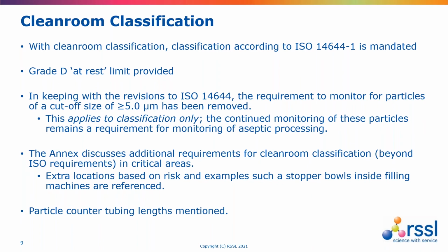And the annex links more firmly with the global cleanroom standard, the ISO 14644 series. This is especially so with selecting particle count locations. But the annex provides additional recommendations that warn against too slavishly following the ISO grid-like approach, and reminds us that we may need to include additional locations based on direct risk to product.